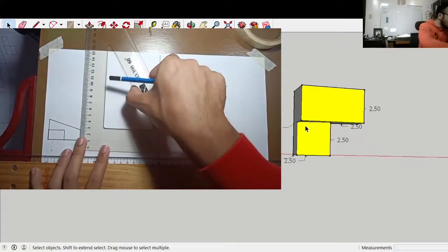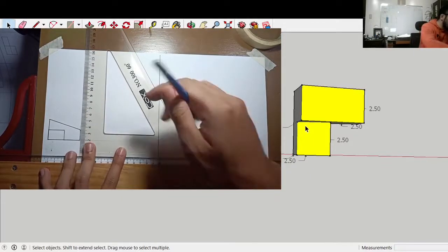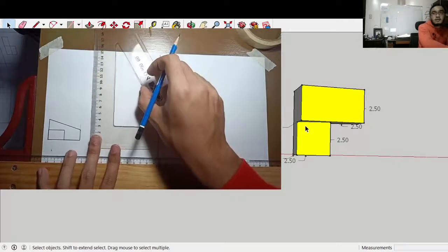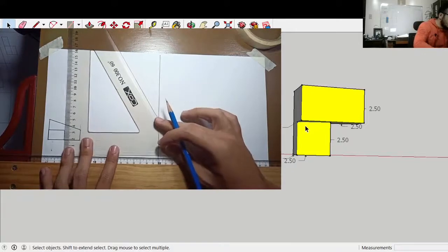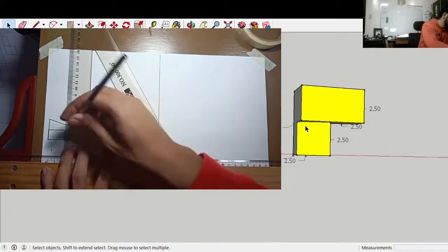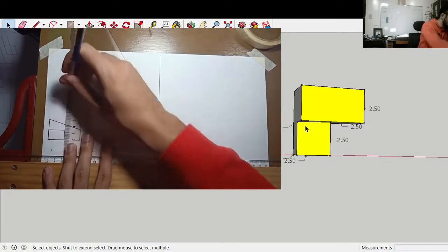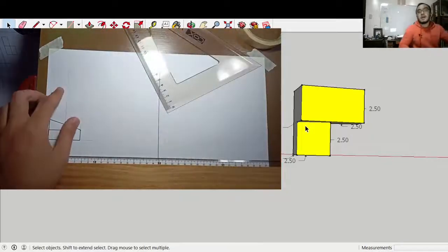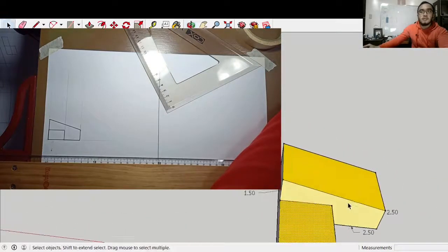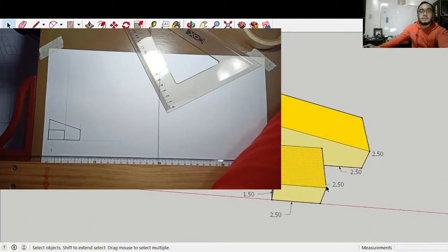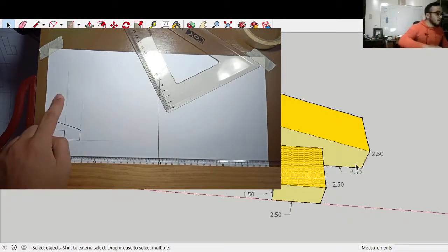So, if this would be your front side view, draw a vertical line along its points of interest. So, that would be that part. I don't know if you can see, but I hope you can see. Then, dito, dinan ko na lang. And as for this part, gagawa ka din ng vertical lines. So, dapat aligned siya. So, there. If these are your lines of interest, meaning that etong point na to ng front view mo, and kapag tinop view mo naman, etong point din na to, dapat aligned din sila. That's why I have drawn these lines that would be showing our points of interest.